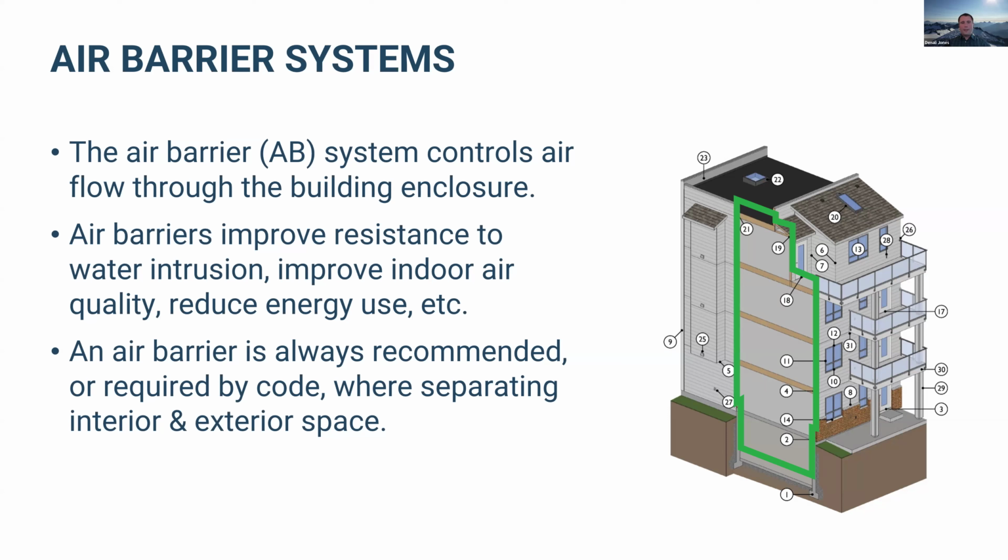So, just summarizing this rain screen wall, we've got this exterior assembly applied to an exterior wall. We've got our outer layer, our inner layer, and the cavity in between that needs to be sufficient for the passive removal of liquid water and water vapor. Tons of different ways to do it. We didn't even talk about glazing systems that are rain screens, but that's a big part of it as well. Things like curtain walls and window walls actually have water management in a rain screen form. They're intended to drain and dry out.